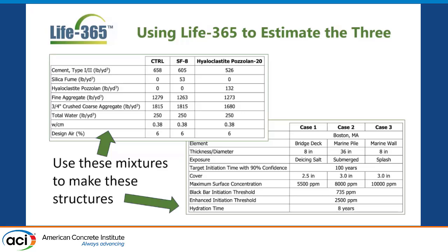Finite differencing is like finite element, where for a slab like this, it'll cut it into a bunch of layers, and each layer is considered homogeneous, and you're then doing the differences between those homogeneous layers. You get to too few layers, and your accuracy goes way down. It goes way, way down. It becomes very, very sensitive to your depth. So we're good here in terms of that cover depth.